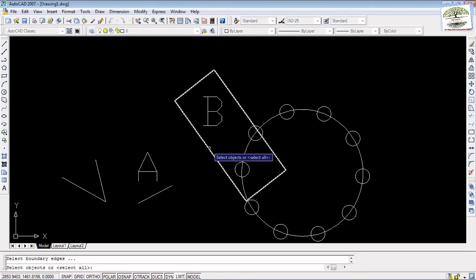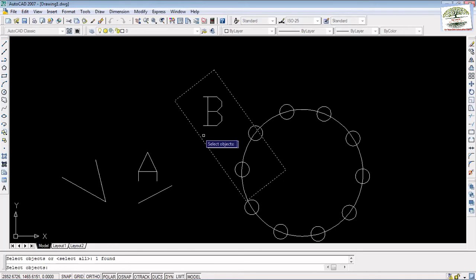We have to extend A to B. Extend, left click, come to B, left click, right click, A, take your mouse to the A and left click. Bingo. So this is what actually can work with the extend part. And now let us move this part.